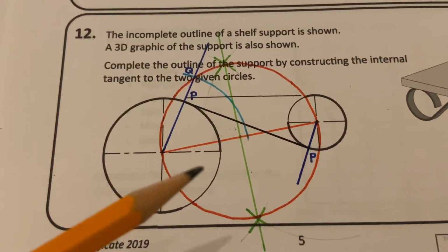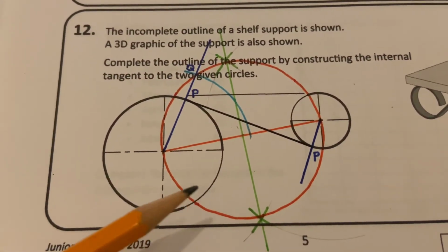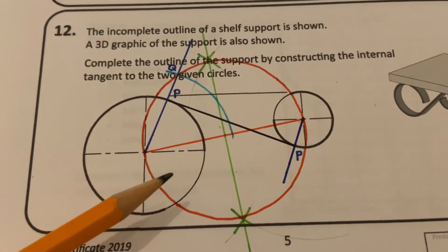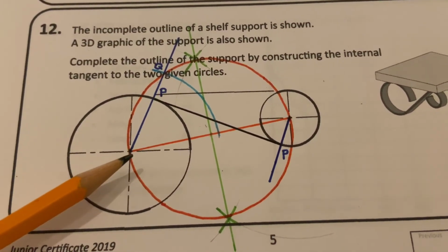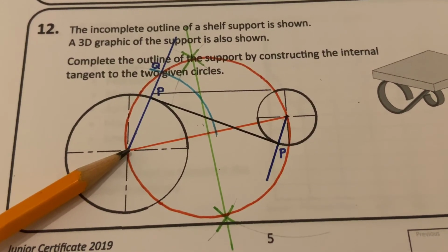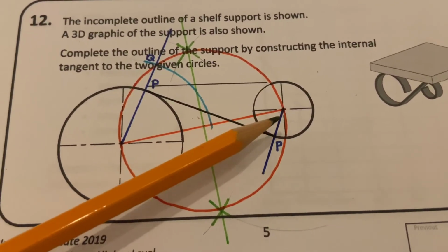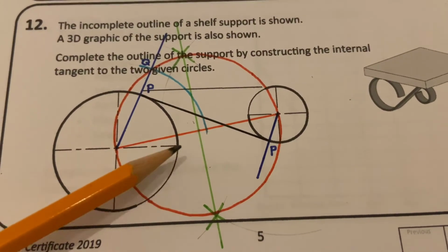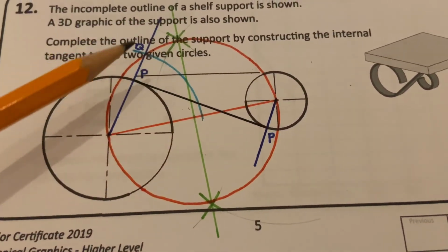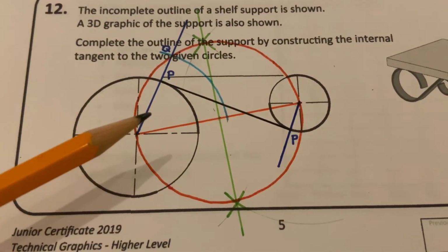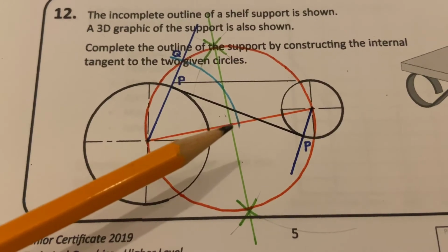Now, there is quite a bit in this, and tangents to circles, the construction can seem a bit complicated, but it is all based on a semicircle. So the first thing that we did was we draw from the center of the big circle to the center of the small circle. Then once we've done that, we bisect that distance and draw on the bisector, and we draw in this semicircle here. Now, after that bit there is very simple and straightforward. There's no complicated issue with that.